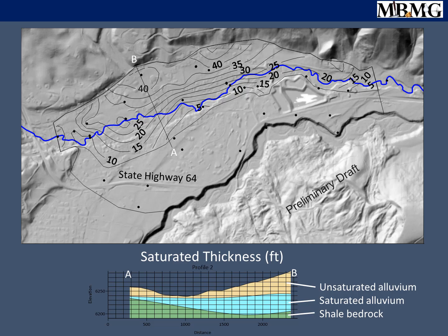So we tried modeling this all the way down to this line because this is a thinner zone, but as you can see in the cross section, it's getting very thin and it's tilting up at a steeper angle, and it became problematic. So instead we had to cut this chunk of the model out, but even though we took about half of the original model area out, there's still 90% of the water volume retained. Looks like a lake, yeah. Essentially. And then to handle this part of the model, we just inject some water along the southern boundary, and we calculated how much based on our recharge estimates.